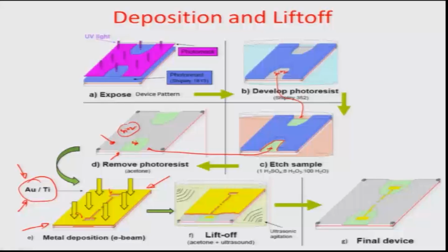So you're depositing this gold titanium layer on the top, and because of which there are certain selected regions which are the cavities as shown here, which is having the deposits of this gold titanium, and then you remove this layer away, so that the gold and titanium has adhering capability to this green Si substrate later on. So they adhere the gold and titanium in this region, and this is how you do printed electronics.